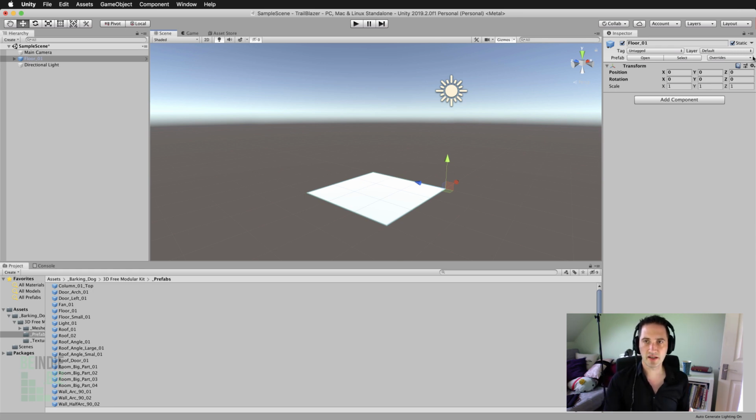If you put a tick in that box, you are telling Unity that this object never moves. So this floor during gameplay, it's always going to be stuck at that position. All the walls, the ceilings, the floors, all of that stuff is going to be fixed in place so we can safely mark that as static. But objects like the player character or NPCs, they should never be marked as static because they have the potential to move around. Okay, great.